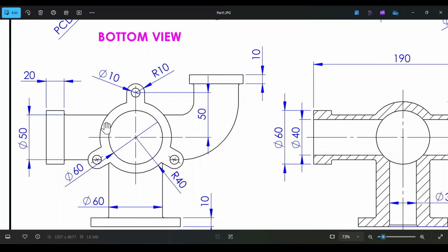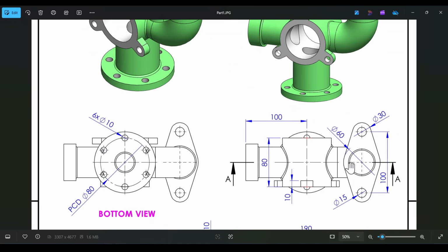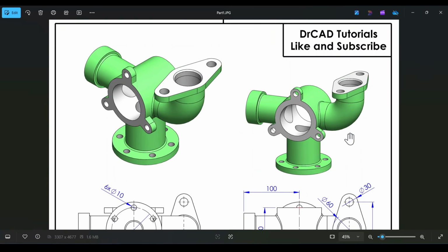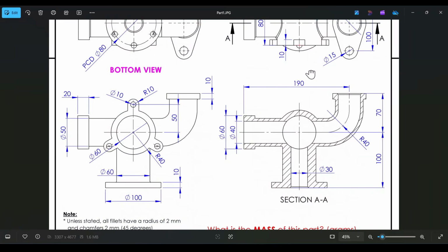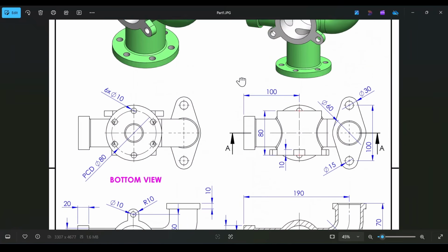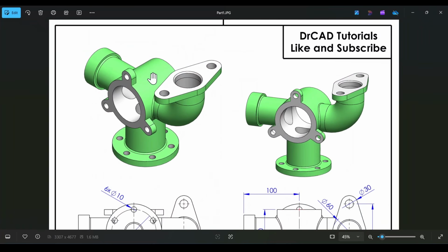And then we're going to create these lug holes using the same process by sketching out the 2D profiles. For the other two copies, we're going to be using the circular sketch pattern tool. And then we're going to use the extrude boss base tool to create the thickness here. Of course, also, we have this oval flange here, the flange here at the top. So it involves sketching, using many of the sketching tools. And that's pretty much it. We don't have a lot of important features for the components. So it just pretty much involves drawing circles and then using the extrusion tool, whether that may be the standard extrusion tool or the swept boss base tool.